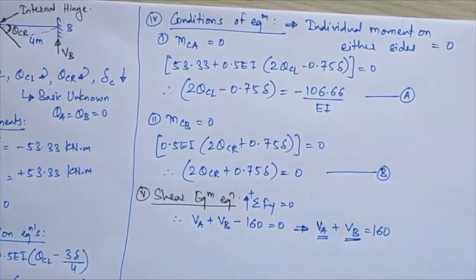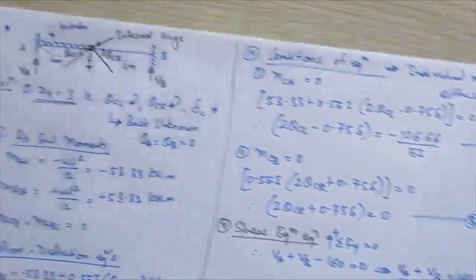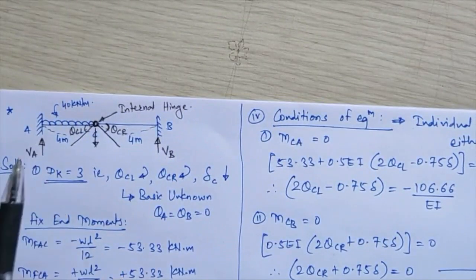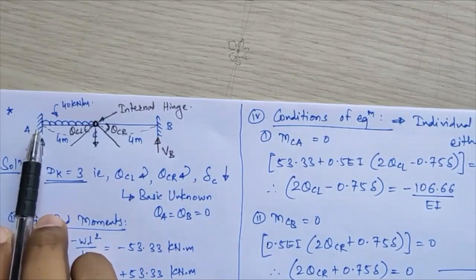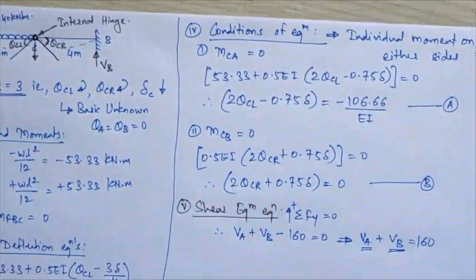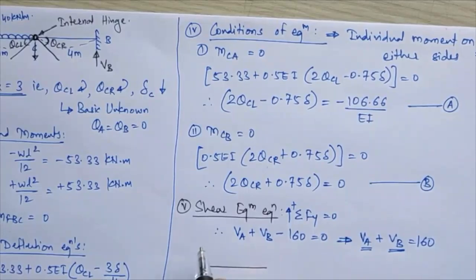Okay. So for that I need to consider the beam equilibriums over there. In case of frames we are considering column equilibrium. Here we will consider equilibrium of member AC and separately our member CB. So first member I am considering here. Okay. This will be your member AC. Okay. Here I am marking your vertical reaction, that is your VA.